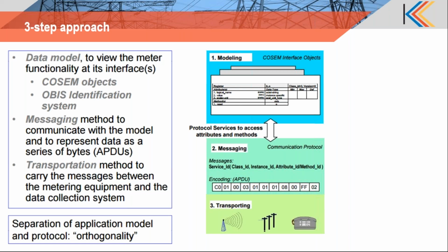or the concept of demand response or load management, monitoring the load and automatically shutting off the load based on the monitored value, etc. So these kinds of advanced metering functions like prepayment, demand response, or connect-disconnect switch or valve, etc. are some of the examples of the advancements that happened in the metering domain. These advancements could be adopted into the data modeling layer of DLMS, and that will not affect the other layers,